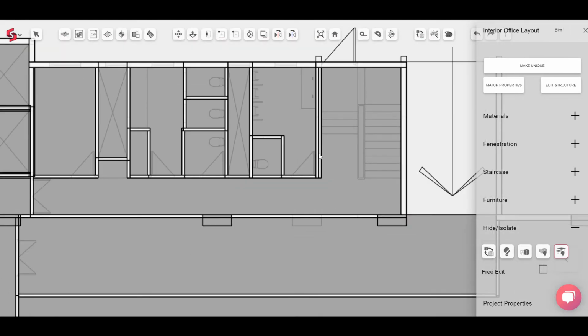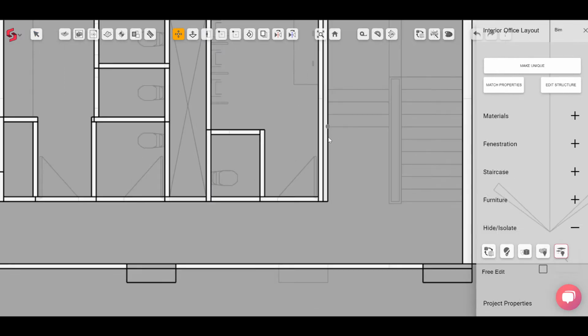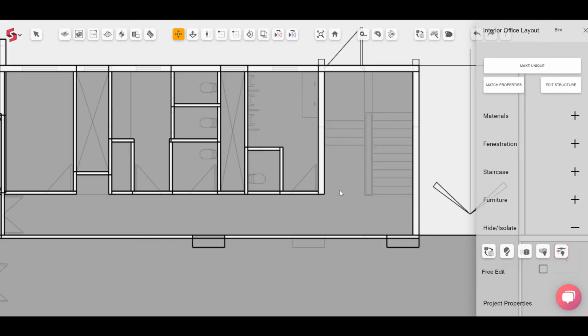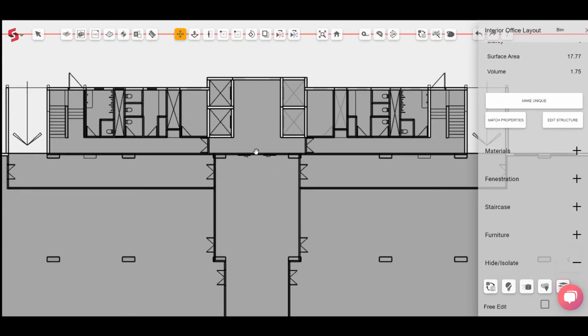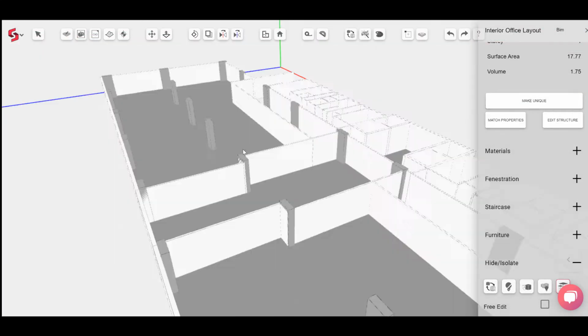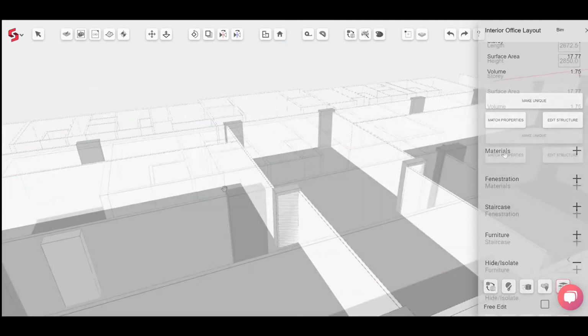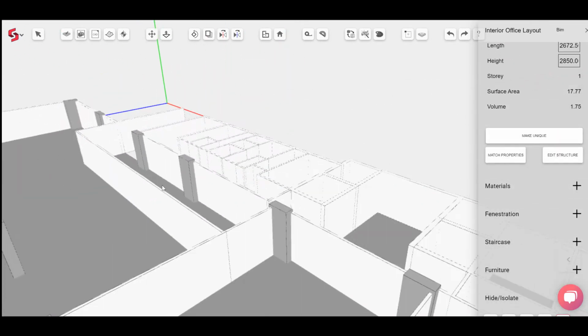Having edited all the walls, let's edit the flow lines. As you can see, the gray portions on this plan indicate the flooring in each space. Go ahead and use the Move tool, select the floor edge and double click on it and move it to the reference line. Check across your entire plan for any other edits that need to be made. You can check in 3D as well to ensure that all the walls are aligned.